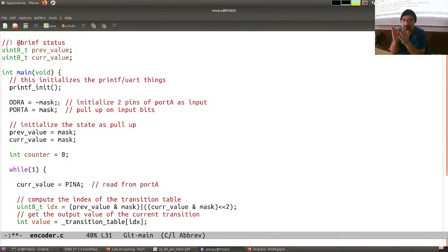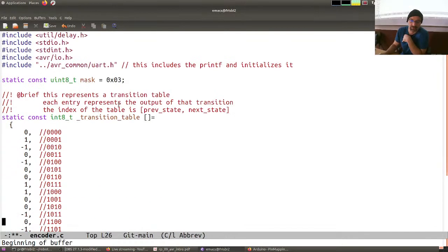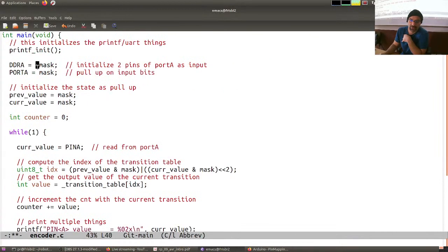And to set these pins as input, I could also be more brutal and simply set the entire port as input, because who cares? I could simply do 0xFF. But you never know when you program a microcontroller whether other pins of a port are in use by some other piece of program. So it's always convenient to do something like a selective pin thing.